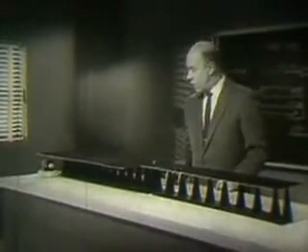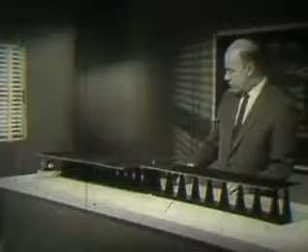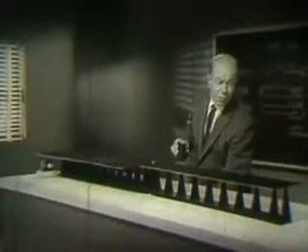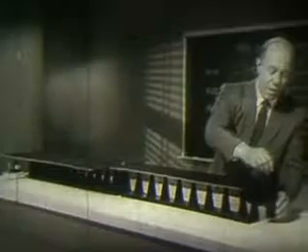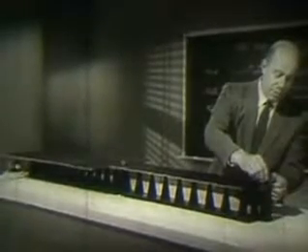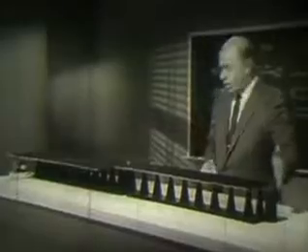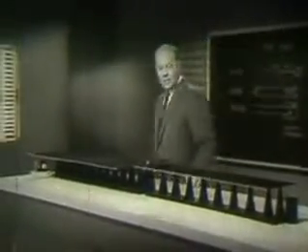At this point, where the two central wires are clamped together with this little clamp, there is an abrupt discontinuity in the impedance of the transmission path. A wave traveling slowly along this medium will suddenly speed up when it crosses over into this one. This behavior is similar to what happens to a beam of light when it emerges from glass into air. Now, before I show you what I want to show you, let me clip this dash pot down here in a matching position to prevent the unwanted reflections from this end. It's this point here that we're really interested in.